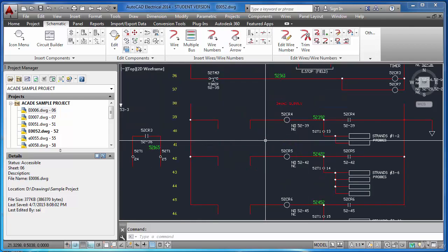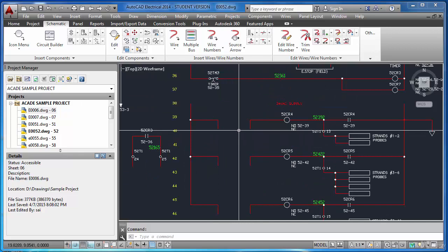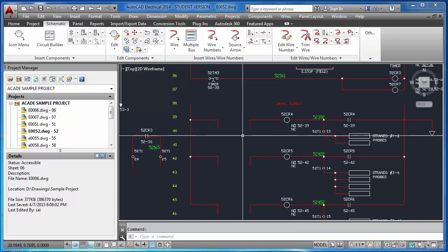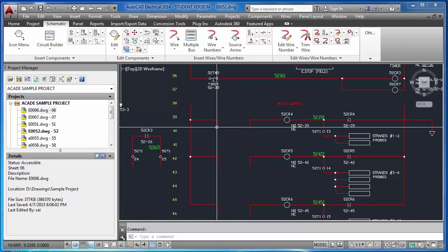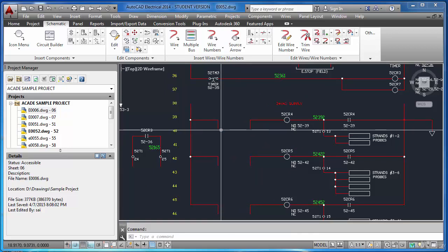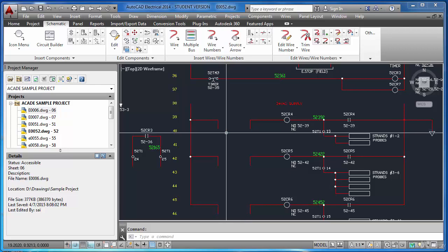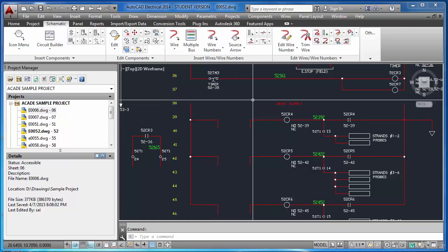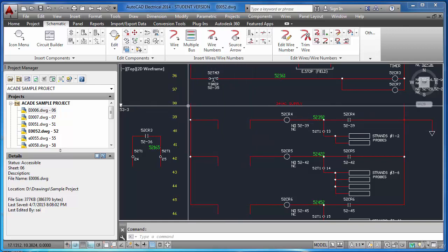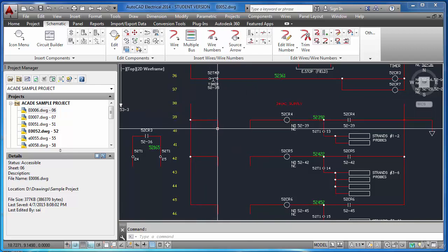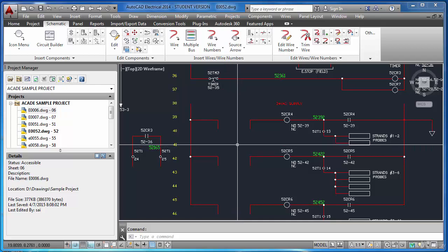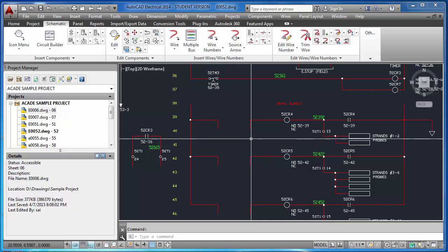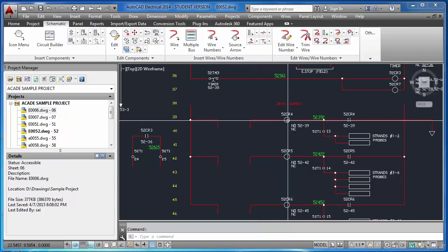and see, there are some open wires in this circuit. You can see, basically we should connect some PLC outputs at this point. What it does mean is, when we provide a 24 volt supply, the phase will come here, and from here it will go to one relay board, and from there it will come here and pick up this control relay.